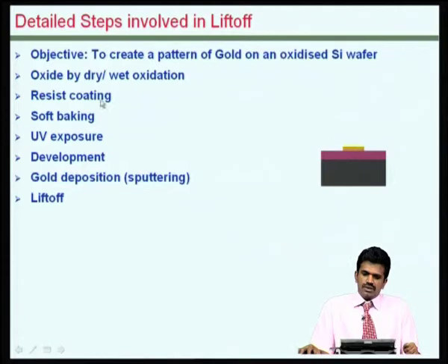So, as you could see, the sequence of events is slightly changed for processing for pattern transfer by Liftoff. And what you have avoided in this particular case is etching of the target, the gold layer.